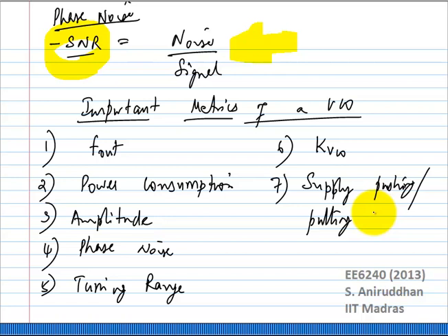Number two, the power supply is not just a pure DC voltage, it comes with its own noise, because the power management IC may have certain switching characteristics, it has certain devices, so it may come with either device noise or it may come with some unwanted signal on top of it. Maybe some spurious tones at the switching frequency of the power management IC. So these are all things which will affect the behavior of the VCO, and you will need to characterize how sensitive your VCO is to these things.